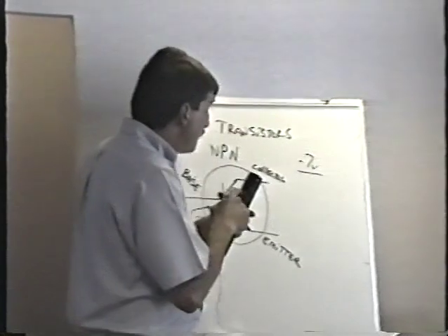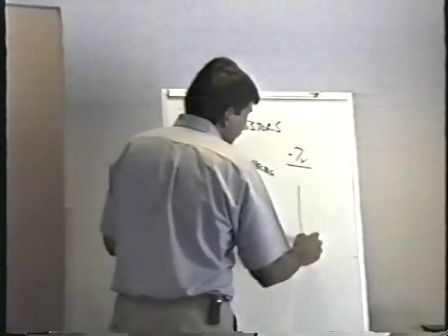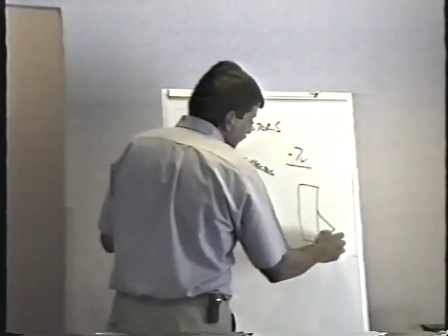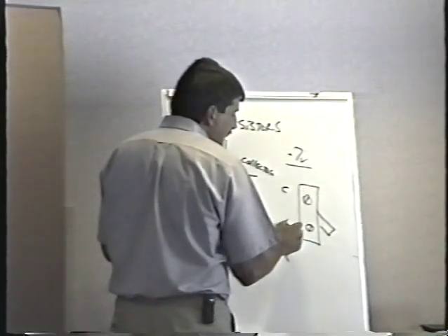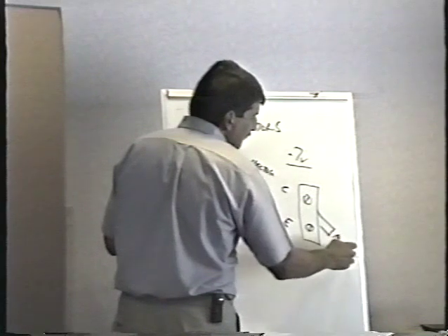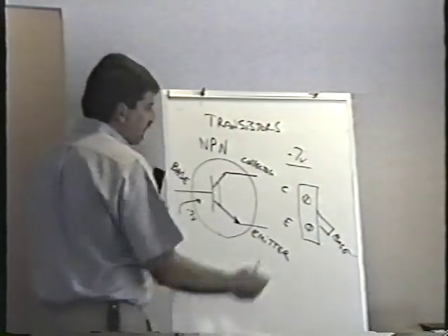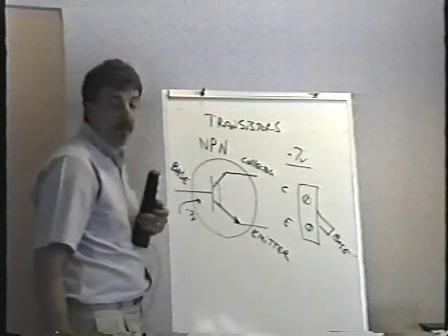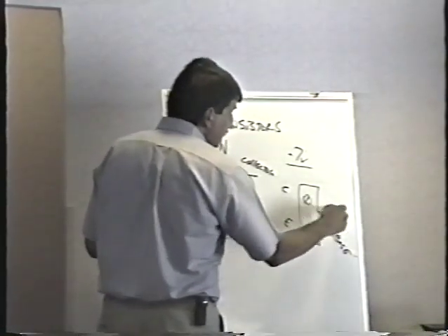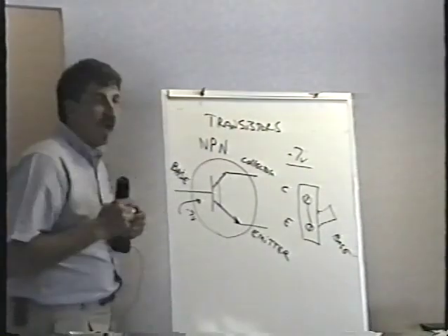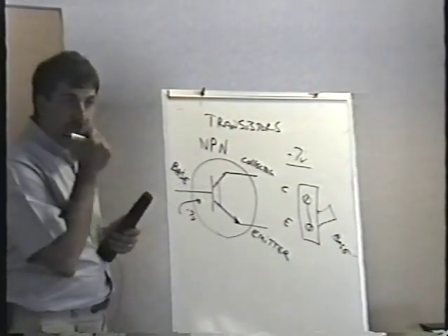So it's the same thing with transistors. When you think of a transistor, just think of it like a toggle switch here with the two screws. There's the collector, there's the emitter, the toggle is the base. When the transistor's off, there's no connection between the collector and emitter. All I do is flip the transistor on by putting 7/10 of a volt on the base, and those two guys are connected together, and that's all there is to it. Very, very simple.